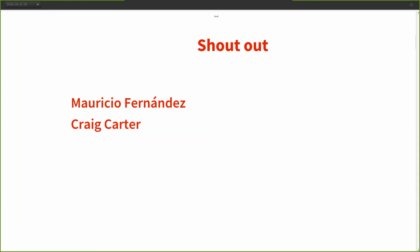Paratosh asks, and this is a two-sided question, given that you are specifying force in newtons, do we assume that the units for X, Y, Z are in meters? Is there a need to specify units for the independent variables? Okay, so units, yes, good question. Glad you asked this. Internally, all PDE model functions convert to SI base units.